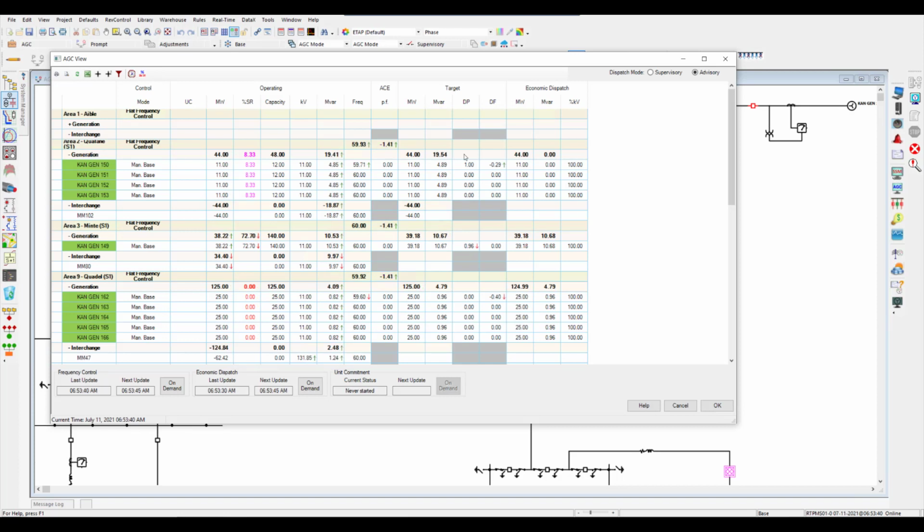So with this, you can clearly see that you can take a model which is in as designed mode, run optimal power flow, get an optimized state of your electrical system as designed, or in case of an expansion or retrofit of an existing facility, then transition that model into real time and use exact same settings to run the optimization as well as other types of controls on a continuous basis.